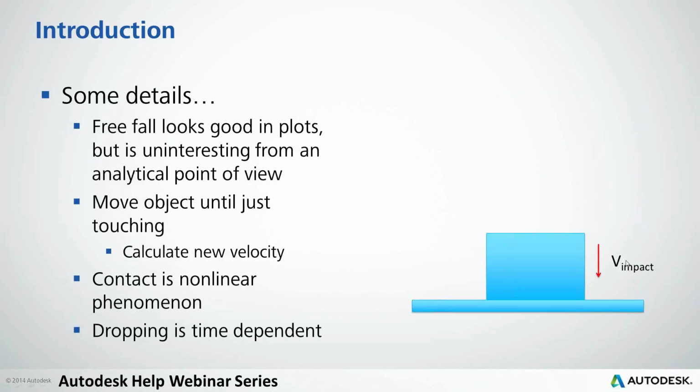And the other thing to note is that when this hits the bottom and bounces up, this is a contact and separation, and it's a nonlinear phenomenon because we have a boundary condition change. Now, there are certain situations where you can pretend that it's in contact and do it without going the nonlinear route. But most of the time, what you're interested in is the interaction of the two parts and how they bounce and hit and twist and rotate. And that becomes a nonlinear phenomenon.